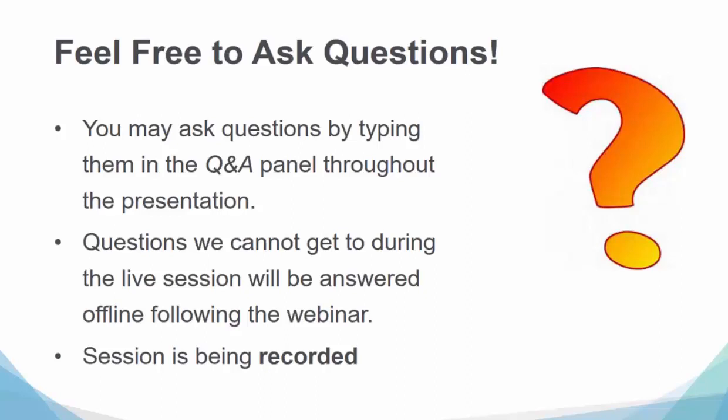You could. And it's not just with the conformal cooling function, but there are a lot of other nice modeling tools that you could use. It's a very robust wireframe, surface, solid modeler. It's all hybrid in that everything works in unison, so it's not like you have to jump in and out of different environments. A surface is a face, a solid is the edges, like a wireframe. It's all very friendly and hybrid, I guess is the best way to say it.